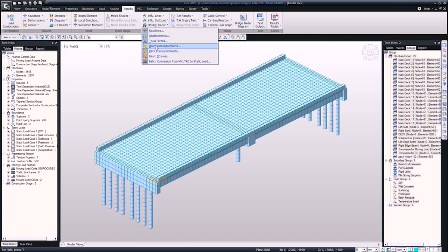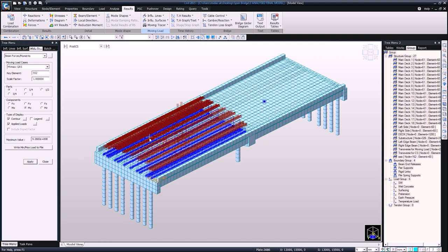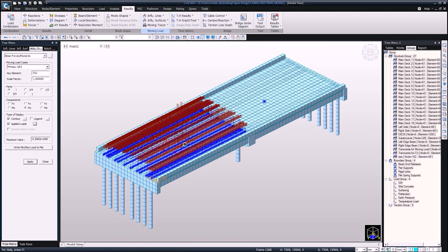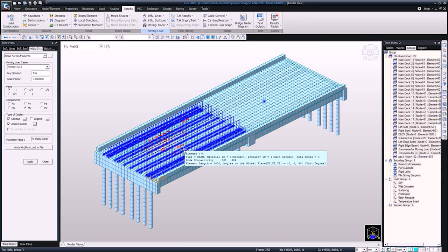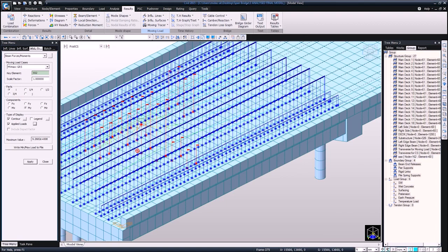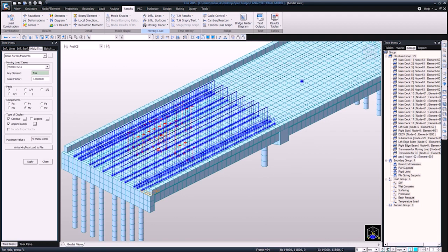So beam forces and moment, and here you can just input the key element, and the software is going to generate you the most severe live loading. Okay, so as you can see over here, let me take off the values so it's more clear. So you can zoom in and you can see the influence lines and the live loads. Also, if you would like to see the coexisting forces for this element, you can simply turn this into a static load and you can check these.